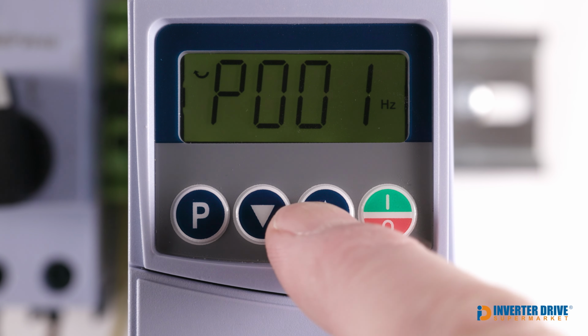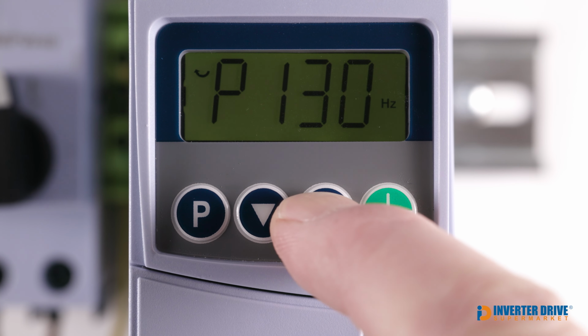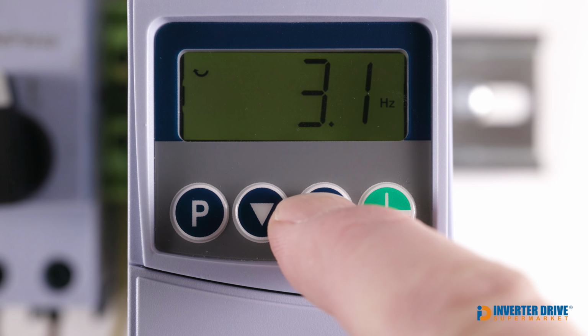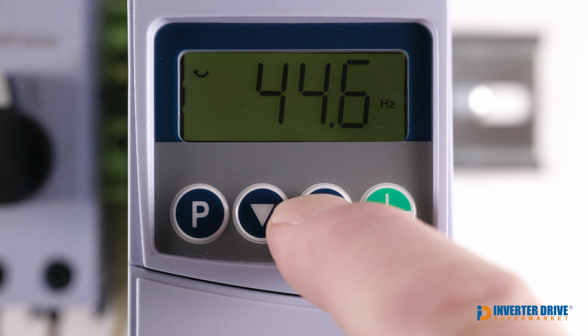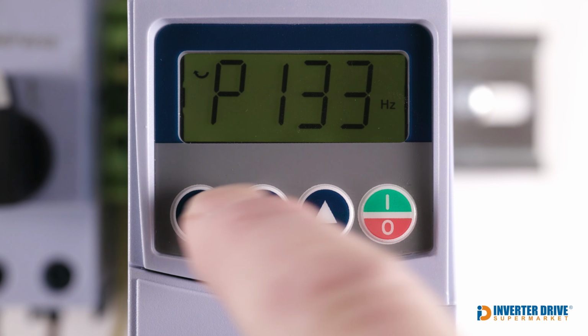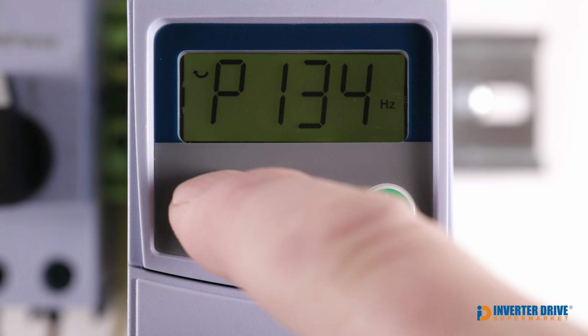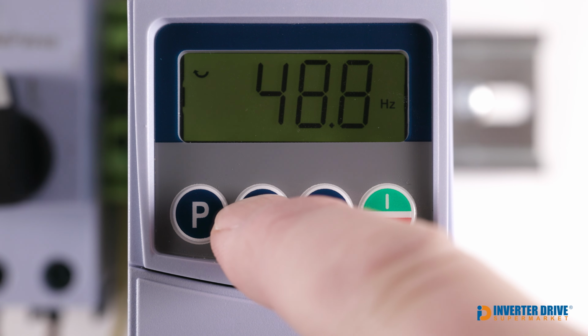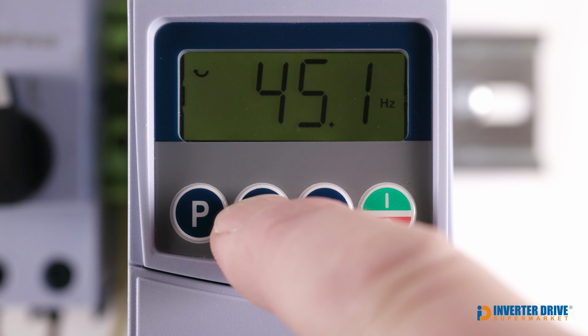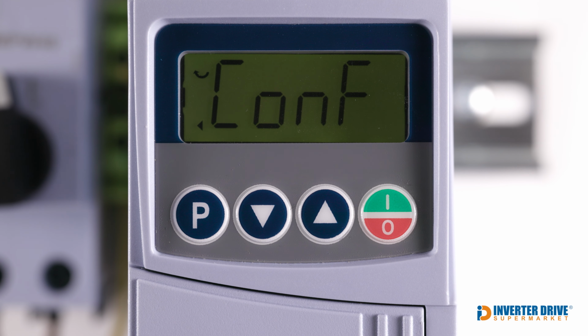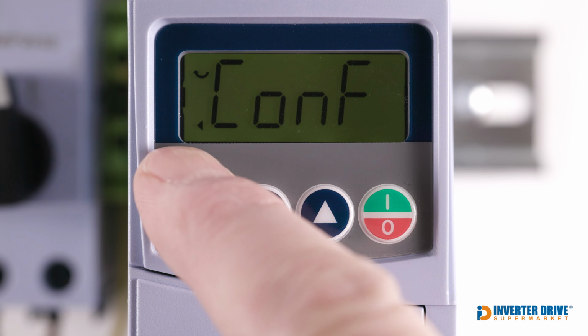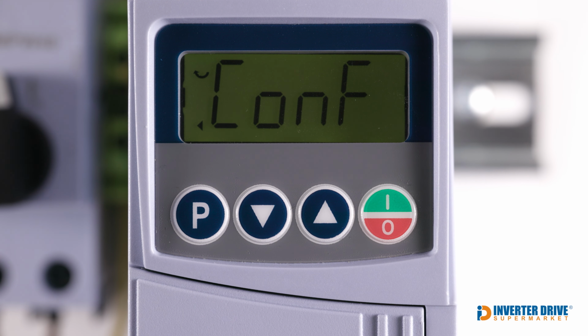The minimum and maximum speeds can be useful if you just want to run at a single fixed speed. You can set both to say 45 Hz, start the motor, and that's the speed it'll run at, no faster and no slower. If I try to set P134 to a value lower than P133, the inverter returns a configuration error. This is to be expected as our maximum speed must be higher than our minimum. A small arrow is then shown on the left to indicate that there's a conflict and it needs to be fixed. Press P to acknowledge.